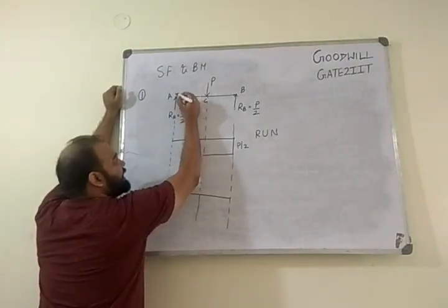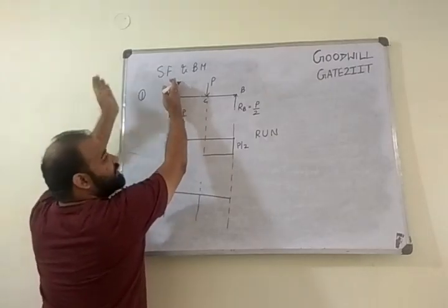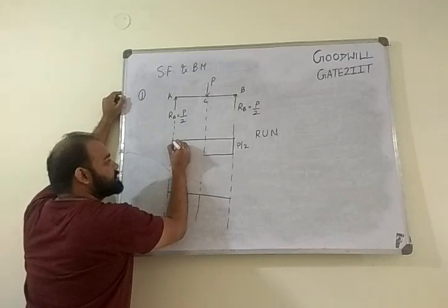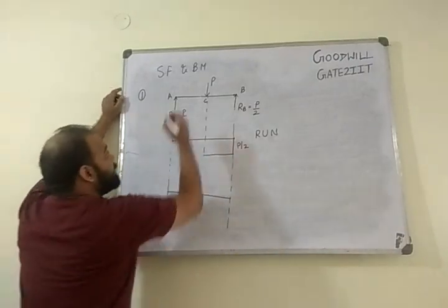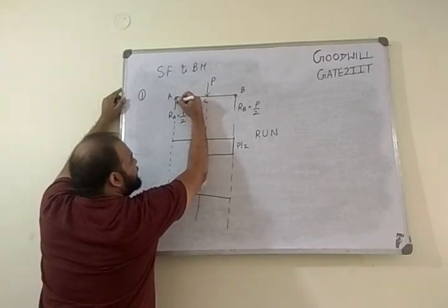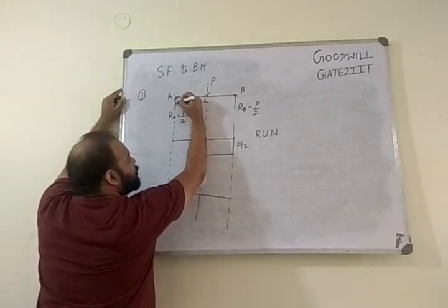I am standing at point A. Now see only on the left hand side. Don't see anything on the right hand side. We don't have anything on left hand side, so my force is 0. Alright? Now go slightly on the right hand side. If you come here, now you observe suddenly there is a force P by 2 going up.